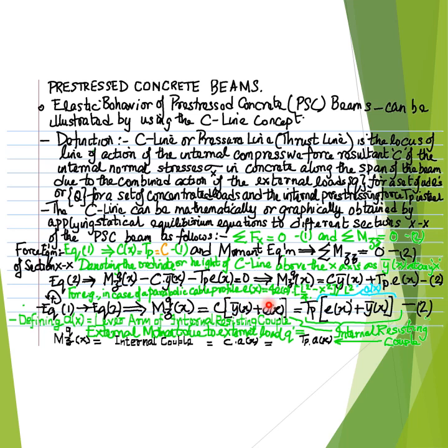A parabolic cable profile may be considered for which the eccentricity function E with the argument x, in case of a pre-stressing cable or pre-stressing tendon profile with a parabolic shape, may be presented by a parabolic function, which we will elaborate on at a later stage in our discussion.